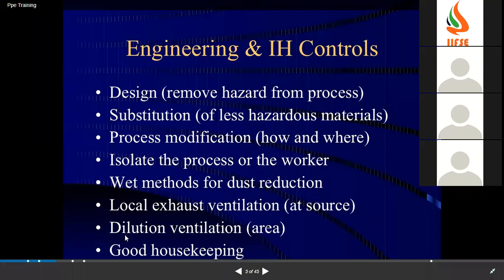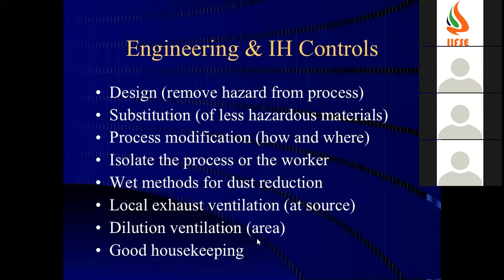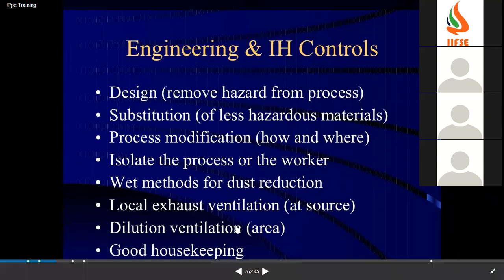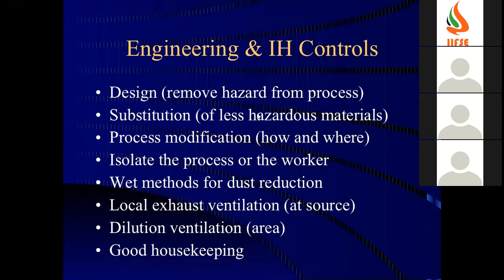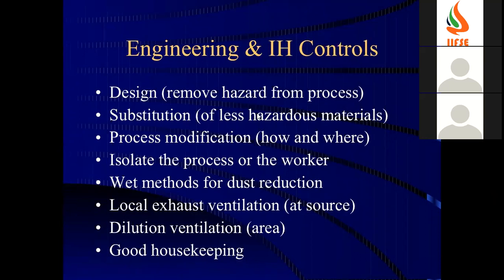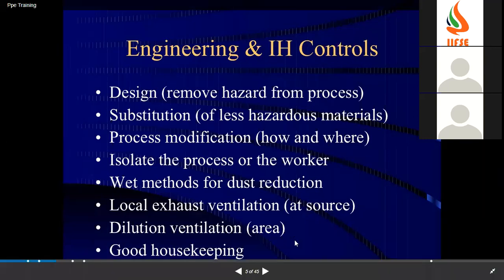Dilution ventilation. What do you mean by dilution? If for example H2S is there, if you can dilute the concentration of any chemical or any gas with fresh air, what happens? It will reduce its concentration. That is also dilution ventilation. Good housekeeping is also a good control.